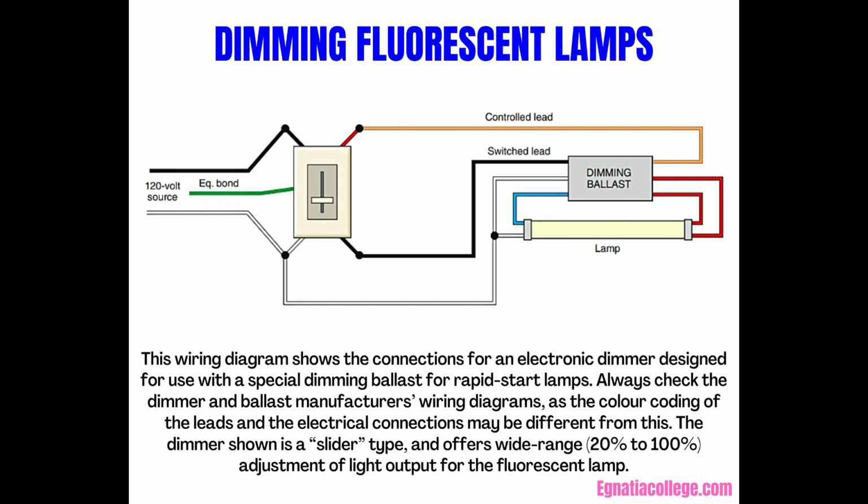To ensure proper dimming performance of fluorescent lamps, make sure that the lamp reflector and the ballast case are solidly grounded. Do not mix ballasts or lamps from different manufacturers on the same dimmer. Do not mix single and two lamp ballasts. Age the lamps for about 100 hours before dimming to allow the gas cathodes in the lamps to stabilize. Without aging, sometimes referred to as seasoning, it is possible to have unstable dimming, lamp striation, stripes, and/or unbalanced dimming